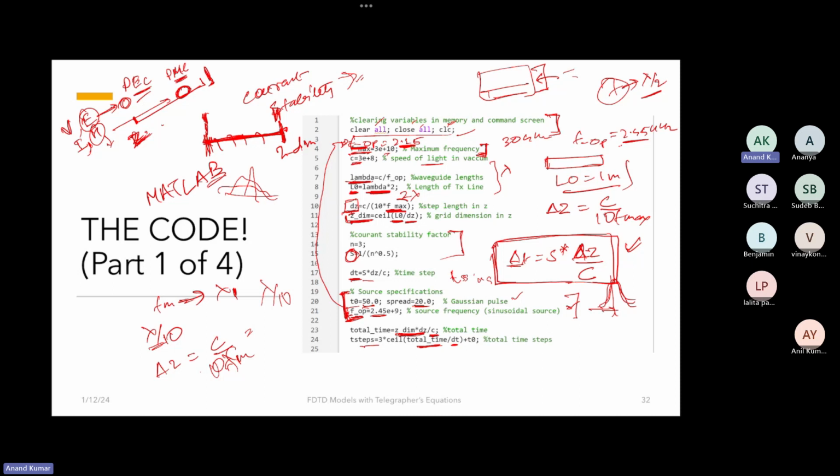So I've got the total number of time steps it will take to reach from one end to the other. Then I have multiplied by 3 so that I have enough buffer to see the reflected wave at both ends, and then added some padding for the Gaussian pulse delay. You can simply use some number like 1800 steps, or just write 5000 steps, and that can also work.